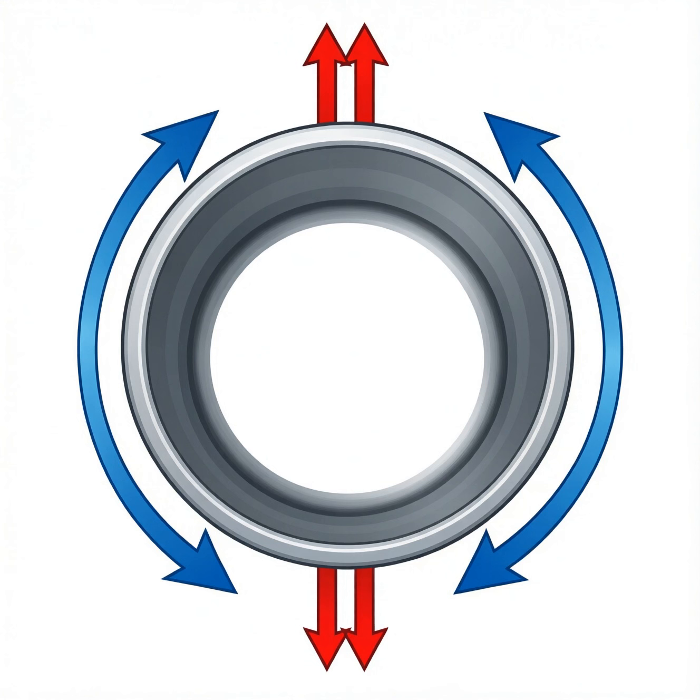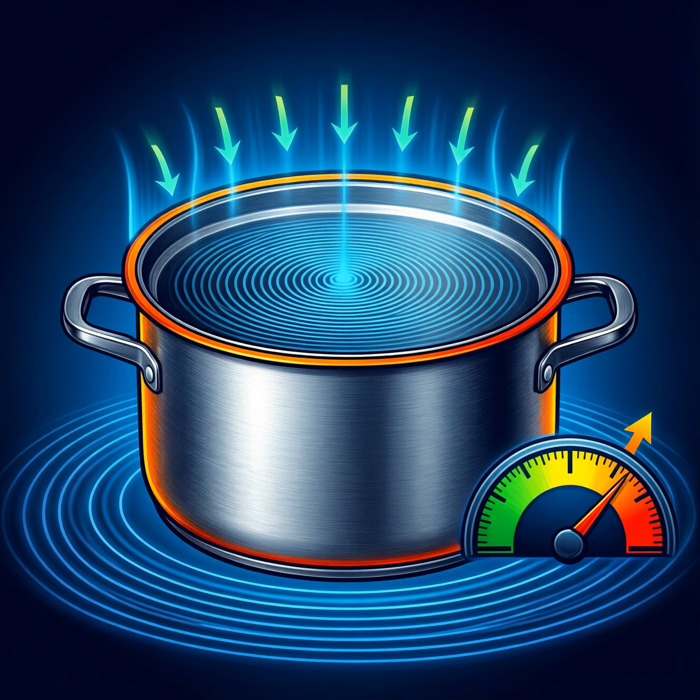When a spoon or whisk is inserted into a liquid-filled metal pot, the fluid exerts varying forces on the pot's inner surface. These forces are not constant. They fluctuate as the stirring motion accelerates and decelerates, creating a periodic pressure pattern that travels along the rim. The metal rim responds by undergoing two primary mechanical motions: shear deformation, where adjacent layers slide past one another, and flexural bending, where the rim arches upward or downward.